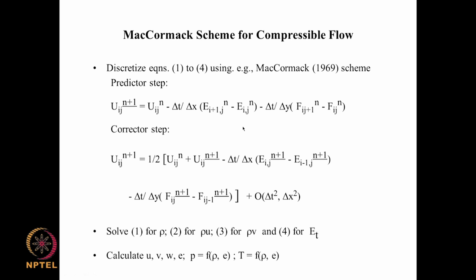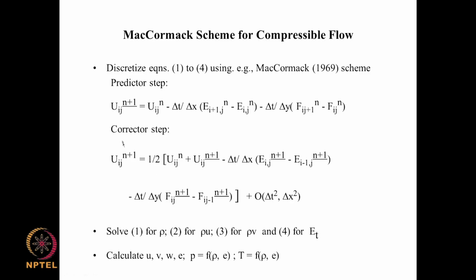So, that is the way that we can write down the scheme here, and the overall scheme is second order accurate in time and second order accurate in space. So, it is second order accurate and not first order accurate. So, you can say that it is more accurate and more likely to resolve the gradients, as there is less diffusion in this particular scheme. So, there is some merit in this.